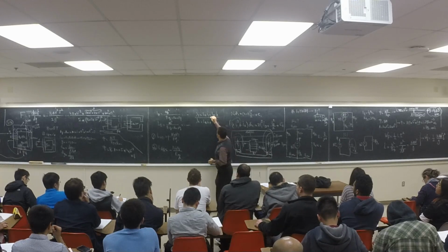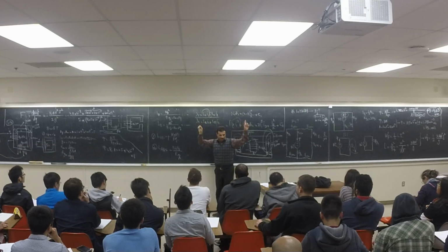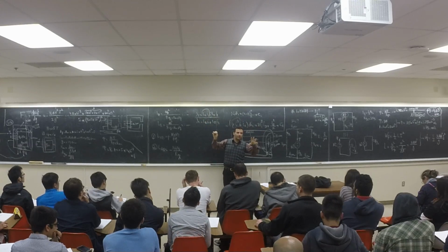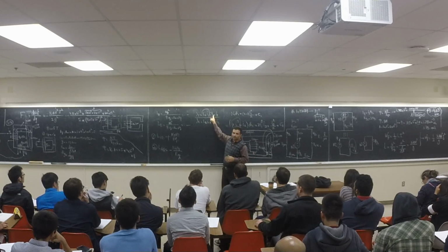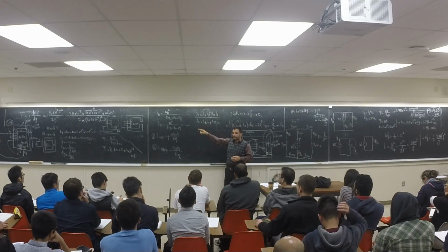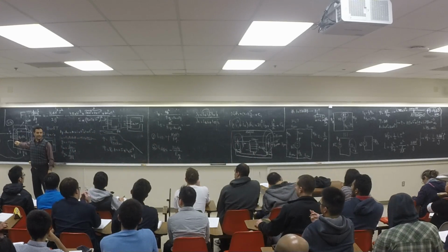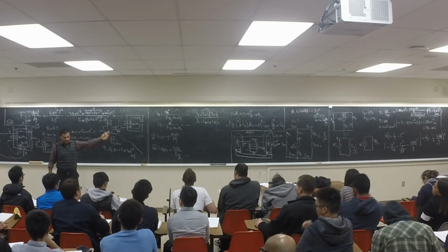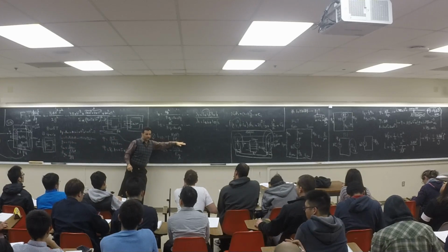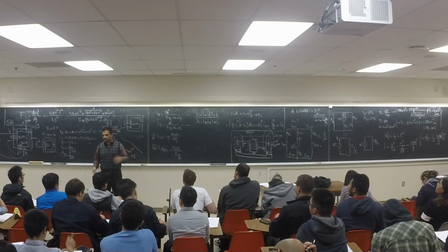So how can that happen? See, this is the flux, right? This is just for winding A. Now the result is less than this much. How can that happen? Only if this one is negative, right? Case 1 is equivalent up to how much? 500 terms. It's more than what A itself can generate, right? Basically L12 is positive. So that's the reason I'm saying here, for case 1 it is positive, for this one it is negative. Now, if you want to calculate the force and those kind of things, you can calculate it.